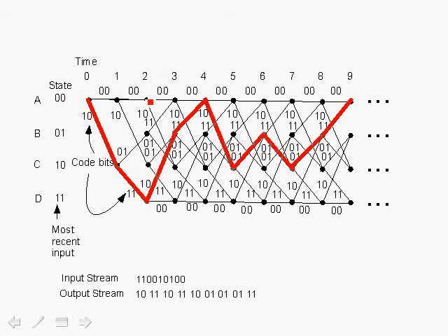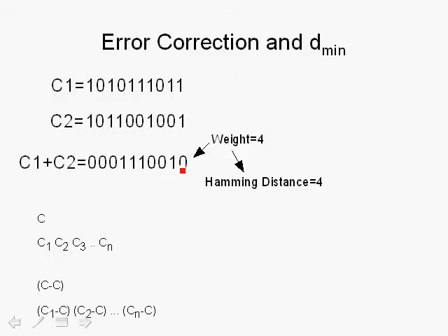However, as you can see, when the constraint length is increased, for example, when it's equal to 7, then you'll have 64 possible states, and the number of paths grows exponentially, and this is not a viable way to decode. More efficient ways to decode have been developed. In particular, we'll talk about the Viterbi decoding algorithm, which is a maximum likelihood decoding, and is very efficient and is optimum. Let's review some of the issues regarding error correction, and we want to also introduce Hamming distance. Although many people are familiar with this material, it's good to review this.